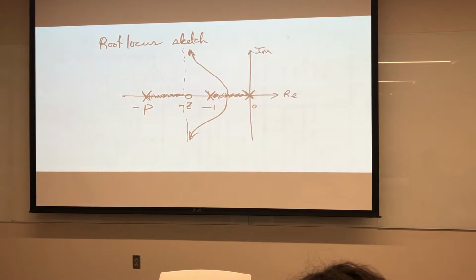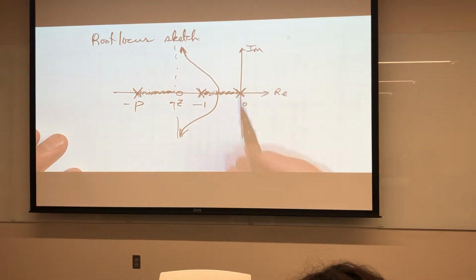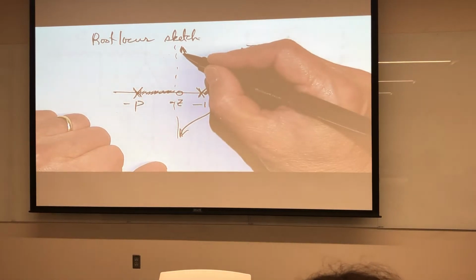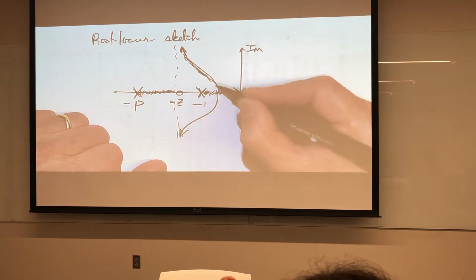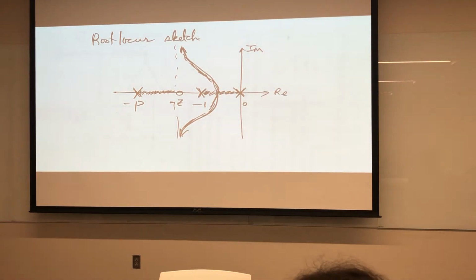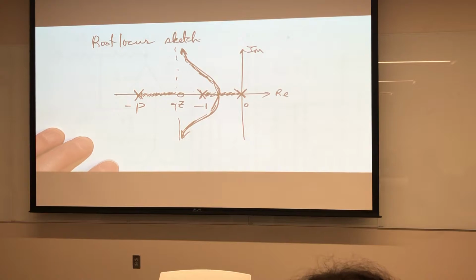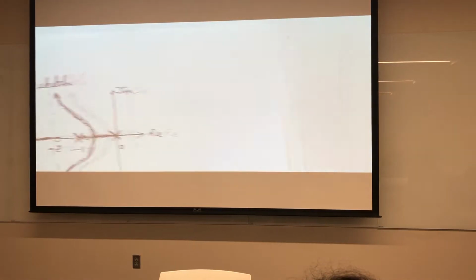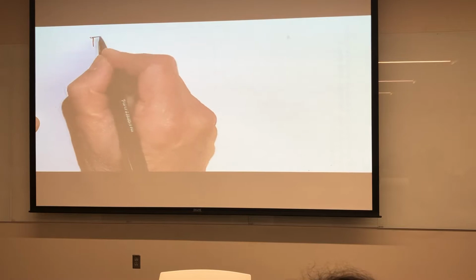stable control system. Okay, so it looks like what I can do is I can have closed loop poles anywhere along these locus or these loci, these lines here. Remember that where the poles are is related to the transient response. So let's look at a design specification for our control system and then convert that back into numbers here. So here's an example.